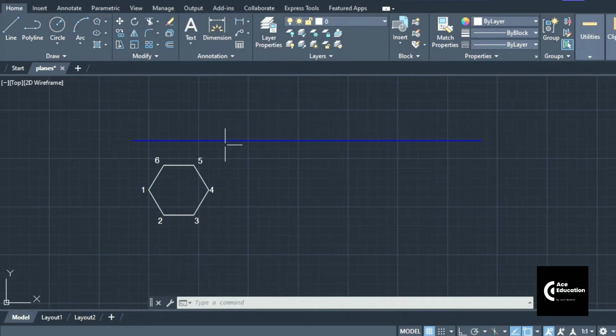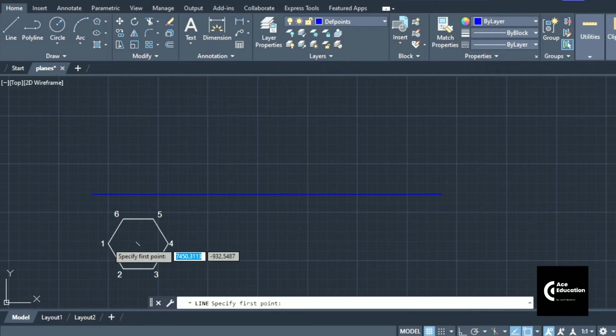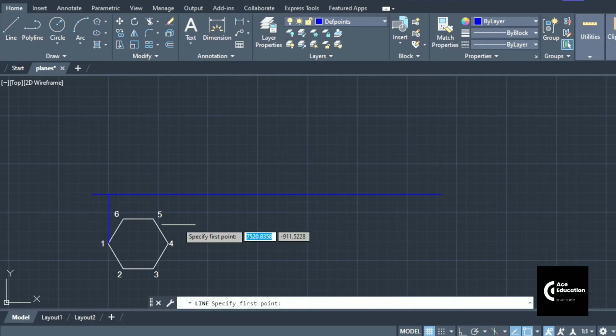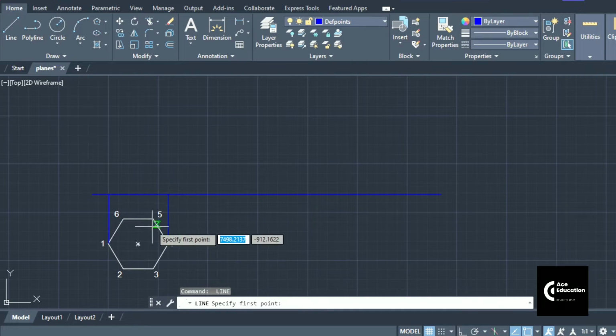Now once we get the hexagon in the top view, to get the front view, we'll take projections vertically upward in the front view. So as it is a prism, we are going to get the rectangle in the front view, which is having axis as 70 mm. So I'll change layer to the projection layer. Just draw the line till this XY line. We'll take projections of all these points till this XY line first.